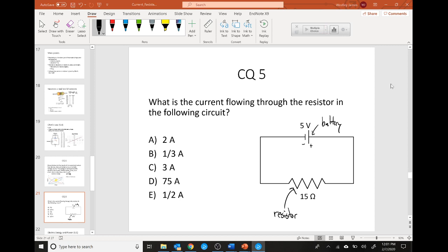All right. So here's the trick to this one. There's kind of an assumption here that I want to clarify that maybe you didn't even realize you were doing. Remember when we had the battery and the capacitor, and we said if the capacitor was the only thing in the circuit, it got the same voltage as the battery? That's the same thing here. If this is my battery, to translate this, we say this side is 5 volts and this side is 0 volts. At every point on this side of the resistor, it is 5 volts.